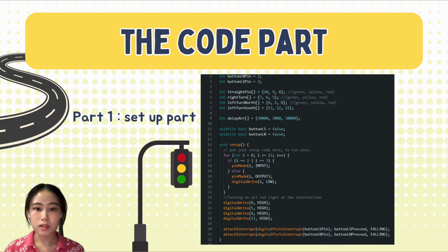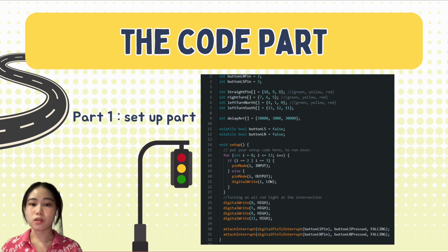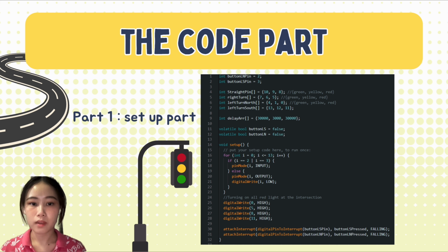We create the time array named delay array. Inside the array, it has 30,000, meaning 30 seconds for green light, 3,000, meaning 3 seconds for yellow light, and the last one, 30,000 for the red light.